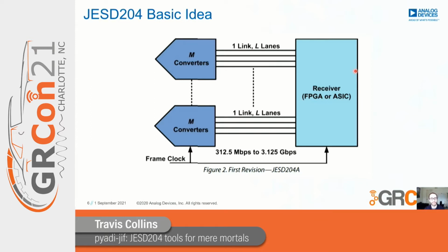Architecturally, this can be really useful because we can separate the converter itself from the FPGA or ASIC. We don't have to have them tightly coupled or tightly placed on a PCB. You could have the ADCs and DACs located up in your tower, and then run, say, fiber directly from the converter down to a processing closet or something similar, where you would have banks of FPGAs or banks of GPUs. So you don't necessarily need a big, power-hungry FPGA mounted next to your antenna elements. You can separate the two if you really want to do that.